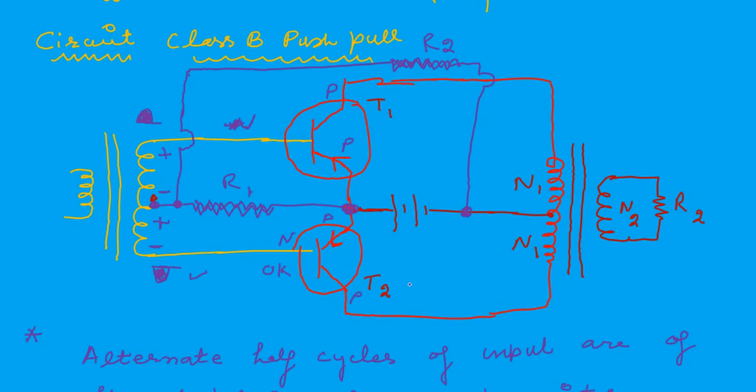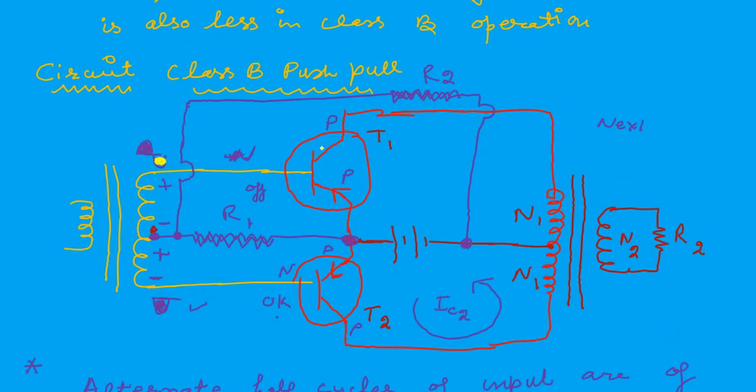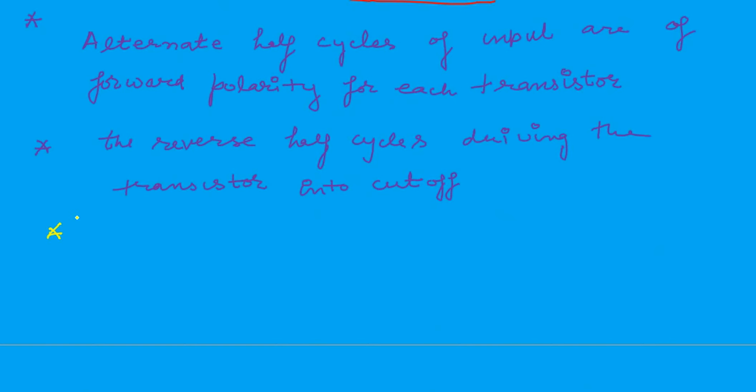So it is good for the lower transistor, current flows to the lower, Ic2. Then when the Ic2 flows, for class B operation the upper transistor remains off. If the lower is on, then when the upper works, the current Ic1 flows, and then the lower becomes off. So each transistor works for one part of the cycle.